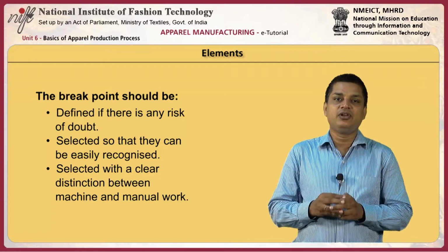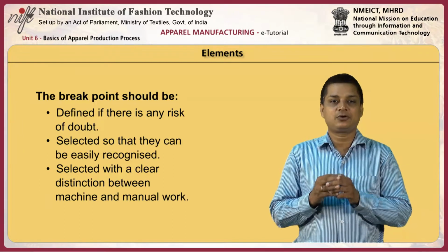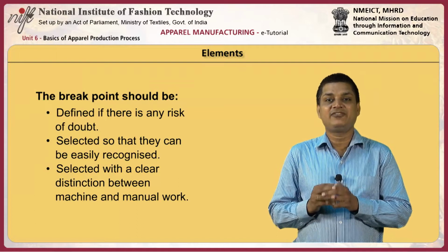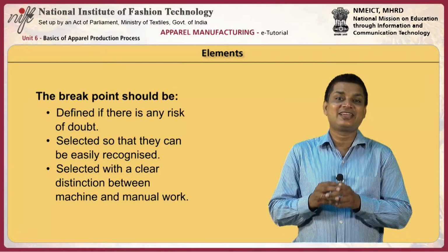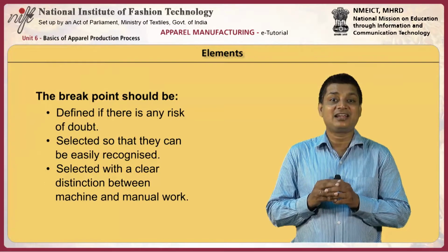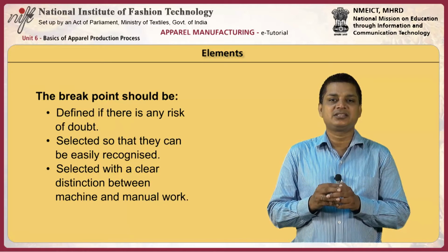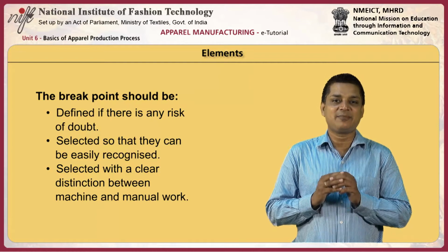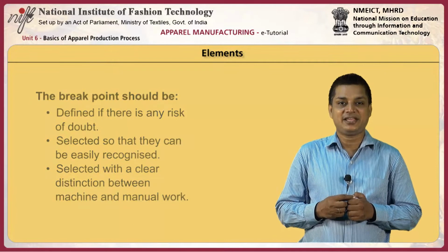Elements should be clearly or fully described on the time study sheet, except where they are widely recognized. The breakpoint should be defined if there is any risk of doubt, and should be selected so that it can be easily recognized. Look for distinctive motion and listen for distinctive sounds. It should be selected with a clear distinction between the machine and manual work. It should not be too short to make timing difficult, nor too long to permit an operator's rating to vary.